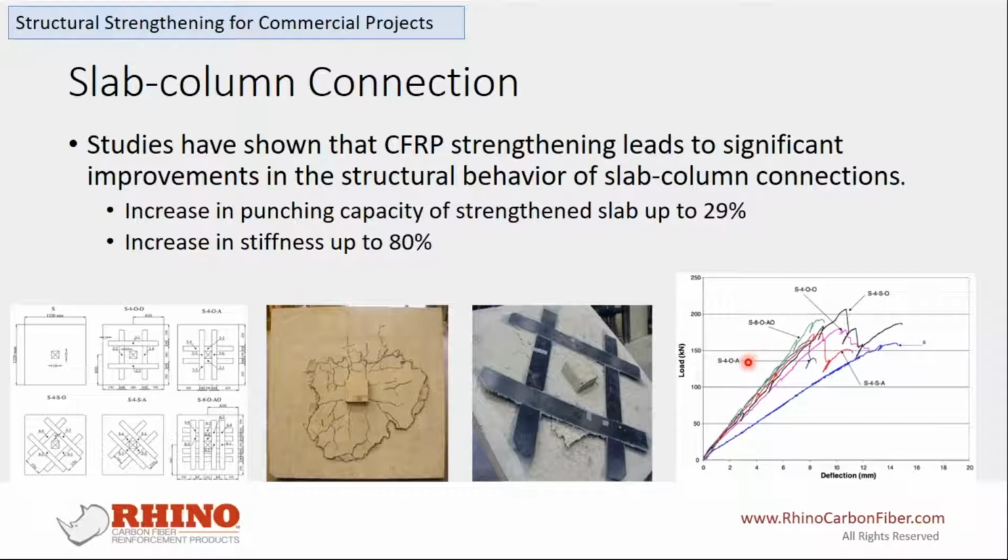If you were with us on Tuesday's webinar, you will know that we always recommend using CFRP to wrap around any opening on a basement wall. A typical example is a window. Any kind of opening on a load-bearing structure is problematic. If you ever use simulation software to see the stress distribution, you will see the edges of the opening are the dangerous zone. If the structure fails, it will likely start from the opening.